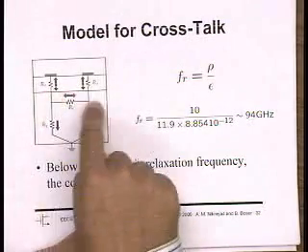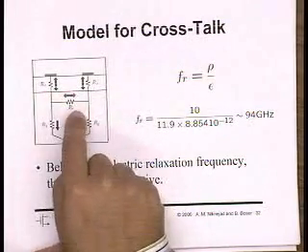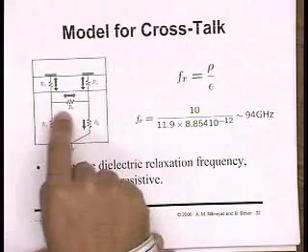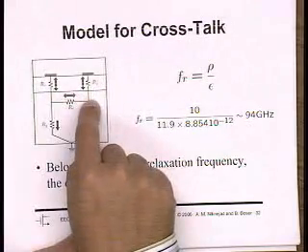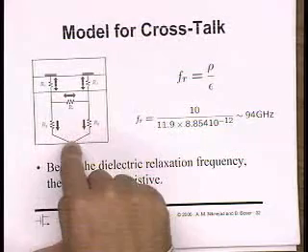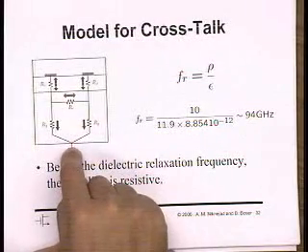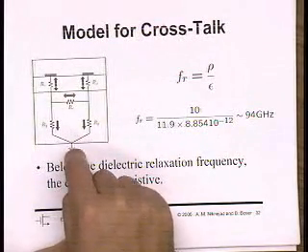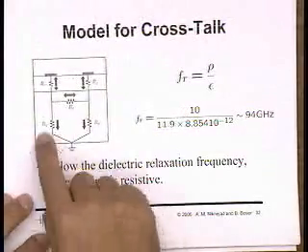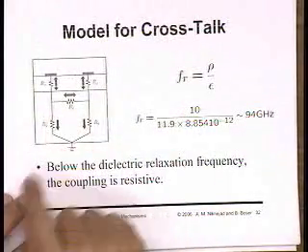And then this resistive network here tells you how much coupling you have from this contact to this contact, and also how much ground current you have in case you ground the substrate. Even if you don't ground the bottom of the substrate, this network still needs to be there. Why is that?